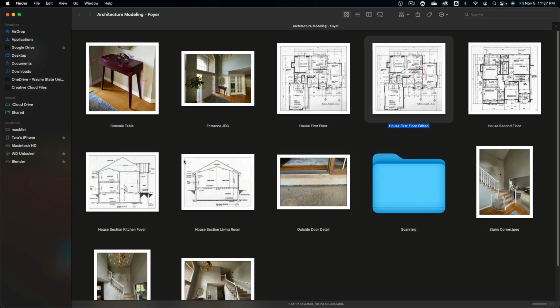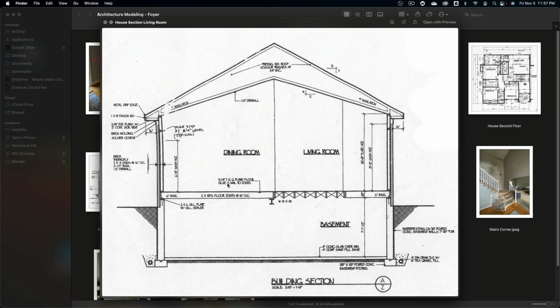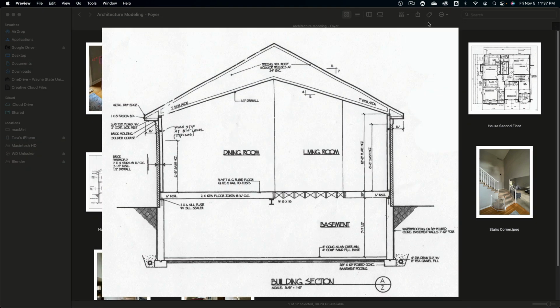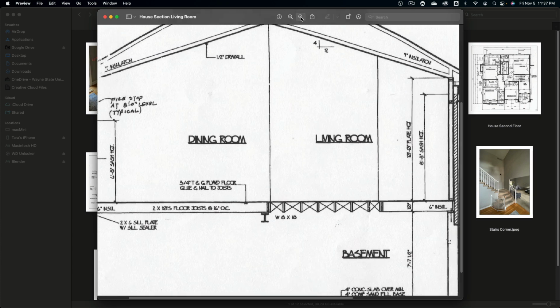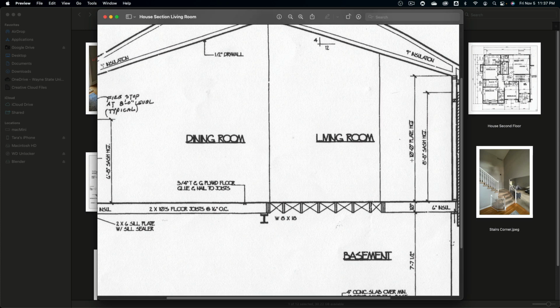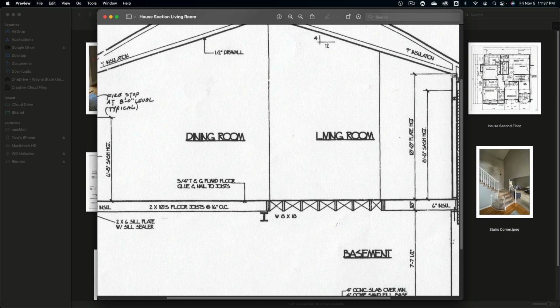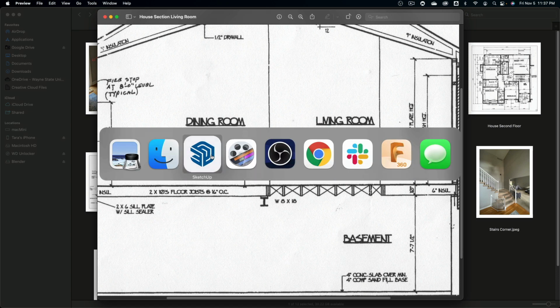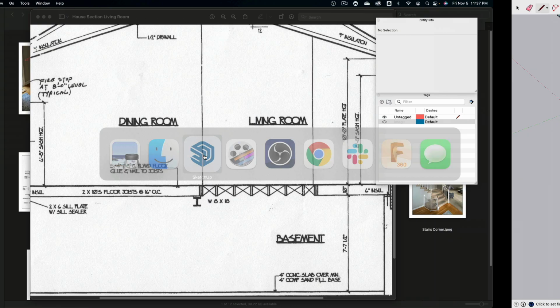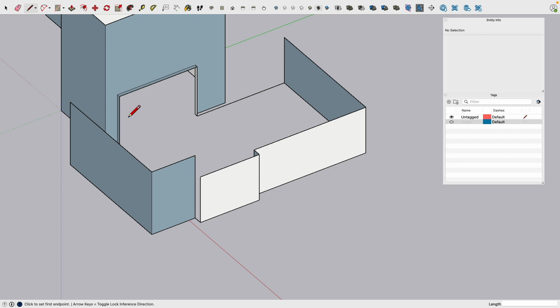Okay, let's go back to what we have here. Are there any types of measurements? So this is a dining room, and there we have actually the measurement on it. So it says, yeah, 10 feet, still kind of like up there. Okay, good. So in SketchUp, this has to be 10 feet. We can do this via a guideline along the z-axis, 10 feet. There we are. Oh, we're actually close.